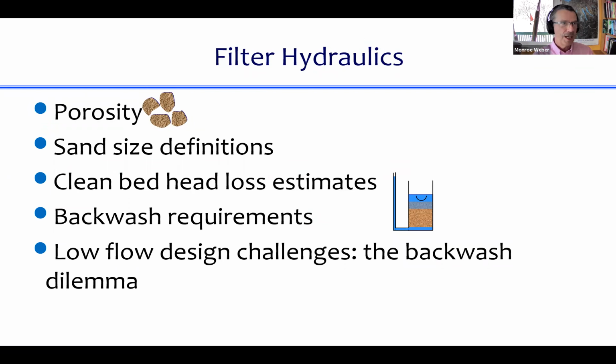The video that I showed also has a clip of Mark Rober, the YouTuber, sitting on top of his spa filled with sand, and then they turn on the aeration system so that it fluidizes, and he just sinks into the sand when it fluidizes. So that's what we're doing inside filters when we backwash them. We are fluidizing the sand, and then the sand grains are moving around, and the flocs that were caught in the pores of the sand grains are knocked off, released. And so we end up getting a clean filter again, and we can start the process over.